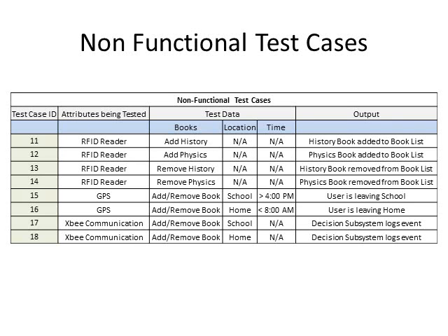Now over here, these are test cases used for testing the hardware itself. In order to test my UART interface, or my SPI interface, I need to connect my RFID reader directly to my Arduino and test whether the history book and physics book have been added to the book list when I swipe their RFID cards across the patch antenna on the RFID reader.